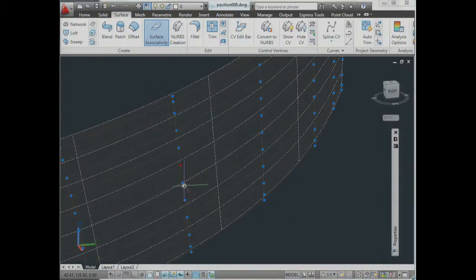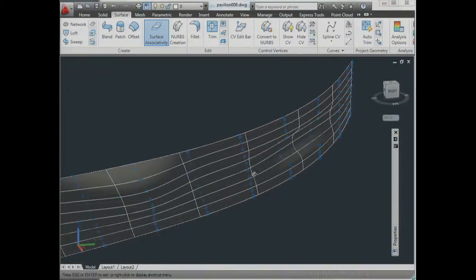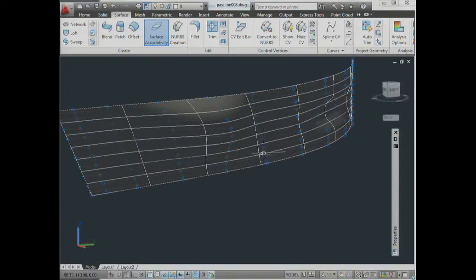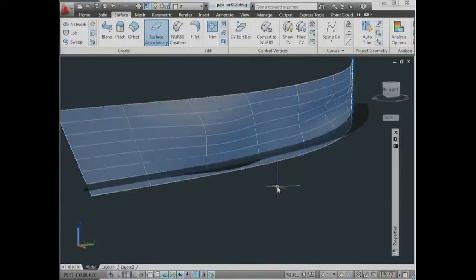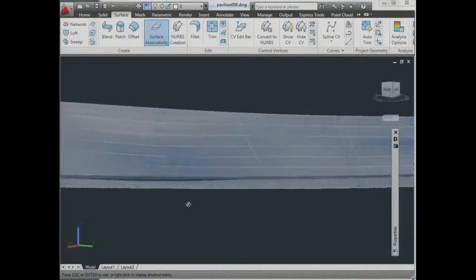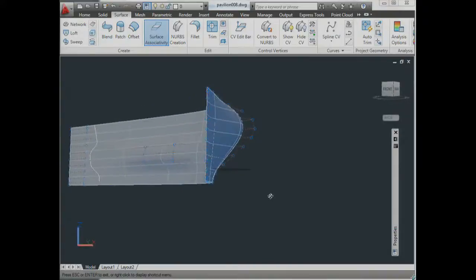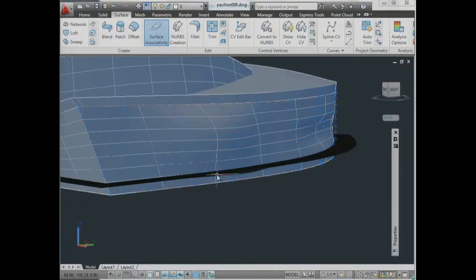So the nice thing is that we can convert any surface into a NURB surface. We can rebuild. We can add more detail, for example, in this case, adding more contour vertices, and just edit, move around in a very simple way. If you're used, for example, to the way 3ds Max deals with edges and vertices, it's pretty similar too. So there's a lot of familiarity. If you learn something in one application, you don't have to learn it again in a different one. And you can get this level of, let's say, flexibility and freedom in a very fast way, right? So my suggestion is keep explicit surfaces as much as you can, but if you really need to have some singularity, just move to NURB surfaces.